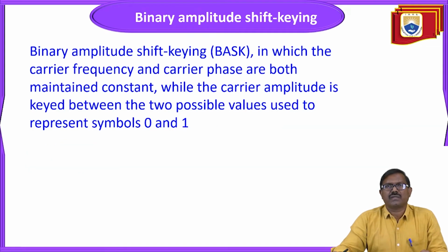The first one is BASK, binary amplitude shift keying, simply ASK, in which the carrier frequency and carrier phase are both maintained constant, while the carrier amplitude is keyed between the two possible values used to represent symbols 0 and 1.